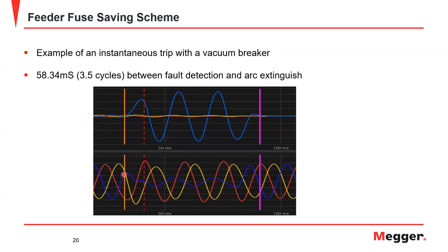Voltage decays immediately. That's how you can usually tell the exact moment that the strike occurred. Current rises quickly as well. Throughout the fault, you can see voltage is maybe 30–40% of nominal on the faulted phase. The other two phases are a little bit affected, but they're almost normal. Okay.